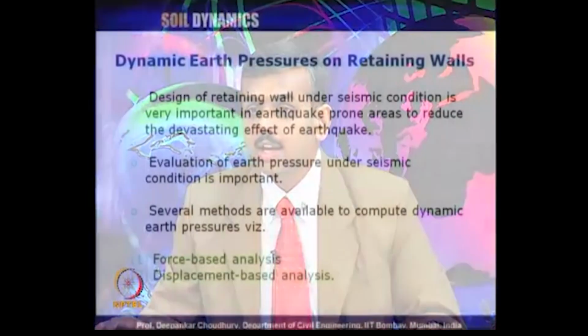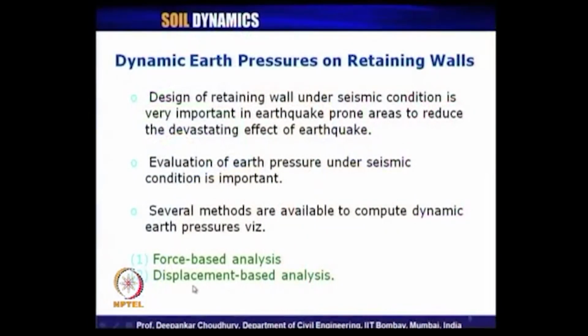Let us look at the slide. And in case of displacement based analysis, what is the difference? Based on the movements of the wall, how much earth pressure is going to generate, because we know the generation of earth pressures is a function of the movements of the wall, right.